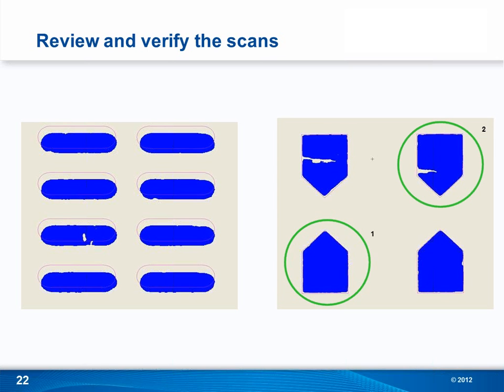When the computer looks at that data, and you look at number 2 there, you can see there are a number of pixels missing in the aperture. That in turn will impact the calculation of aperture size and of the centroid. But I can visually inspect the data before finally using that in my spreadsheet, and exclude specific apertures that have debris in the data field till I get to the apertures that are clean enough to include.